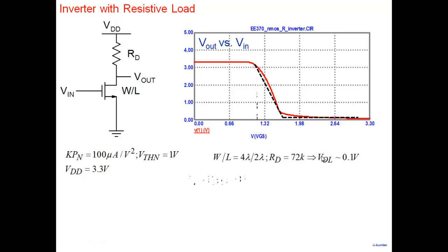All right. So this is there, V0L. The next thing is, what is VIL? To calculate the noise margin, I need VIL. And to find VIL, I have to find a place where the slope is -1. And similarly, to find VIH, I have to find a place where the slope is -1 on this side. So two regions I have to find where the slope is -1.